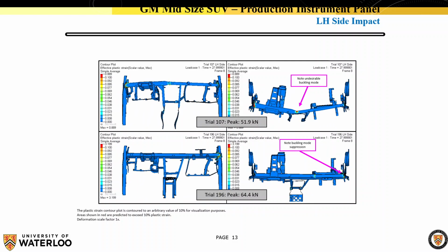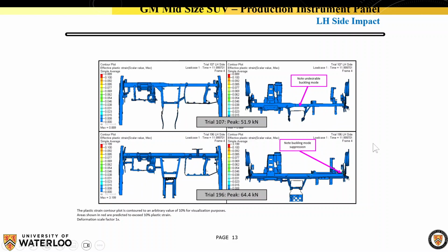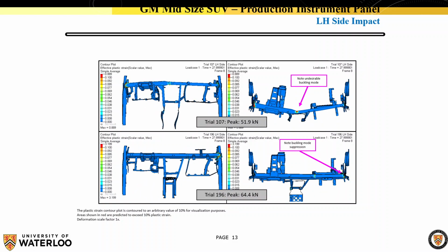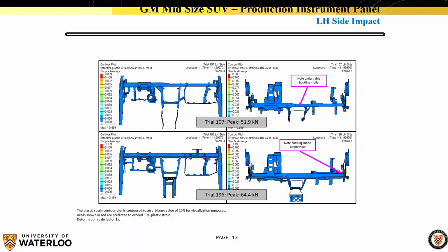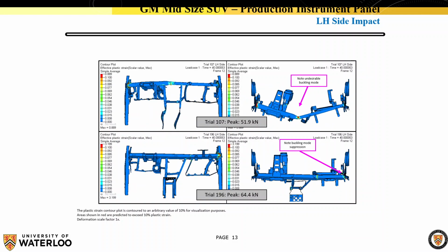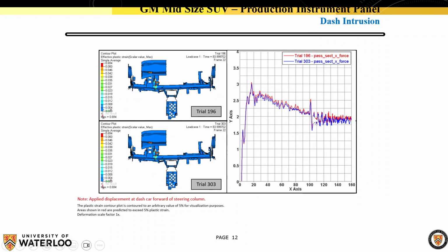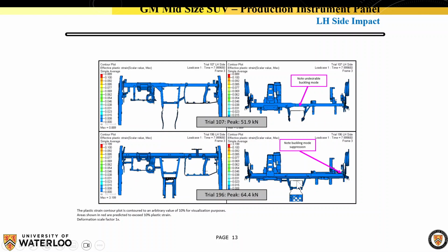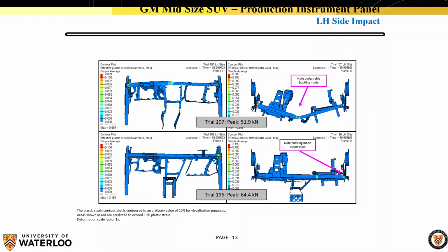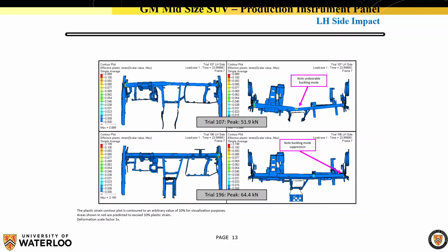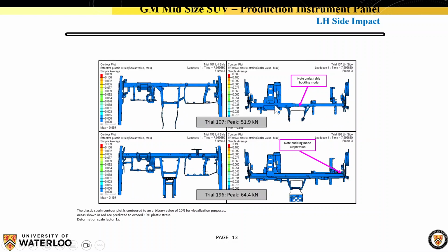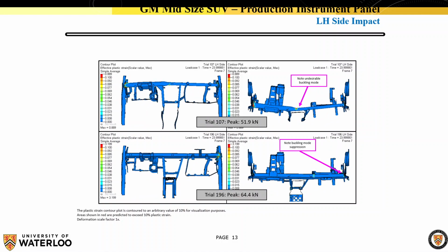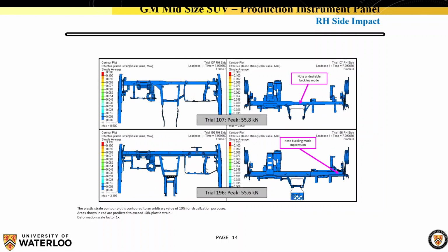This mode is called buckling, which is undesirable because it pushes all of the stuff that's in front of you when you're sitting in the vehicle. It'll push it into the occupant part of the car, and it could obviously cause injury. So a more desirable, let's say, deformation mode here would just be for it to crumple in on itself. That's something that we achieved by changing the actual geometry of this tube that's holding the structure of this part of the car. So that gives you an example there.